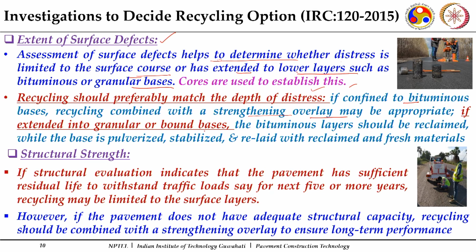If it extends into the granular or bound courses, and an improvement is required at those granular courses, we can reclaim the bituminous materials, and the lower bases can be pulverized, stabilized and relaid, again with a bituminous overlay using those reclaimed bituminous materials on the top.